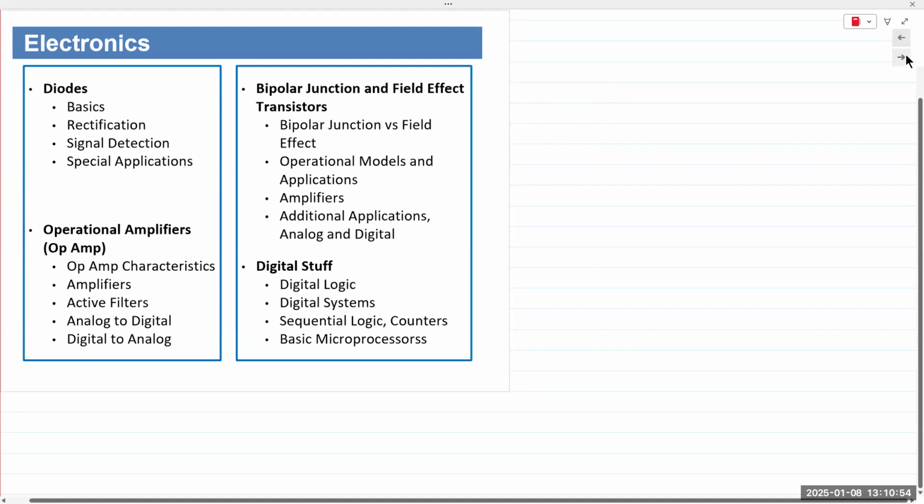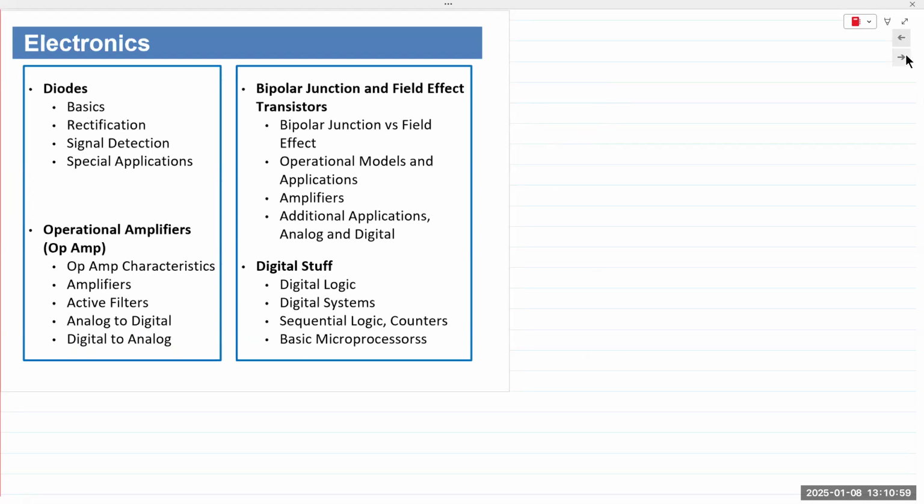All right, electronics. Let's take a step back and think about 201. We learned about circuit analysis techniques with regards to 3 elements, right? We had resistors, inductors, and capacitors, R, L, and C. So all 3 of these are classified as linear elements. The reason we say they are linear elements is because the voltage and current for these elements have a linear relationship.